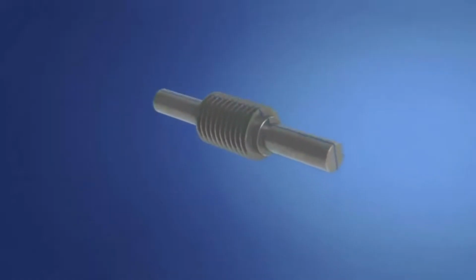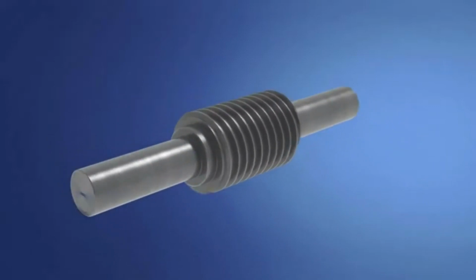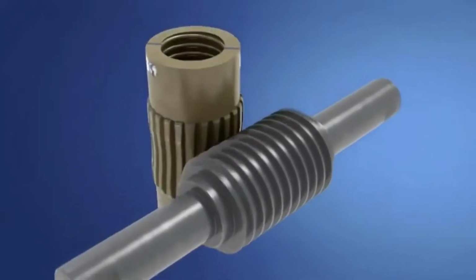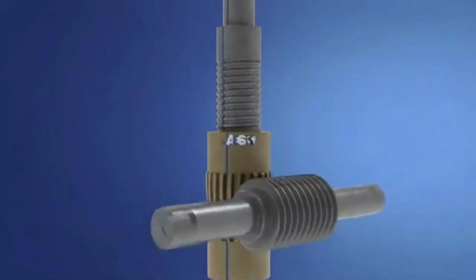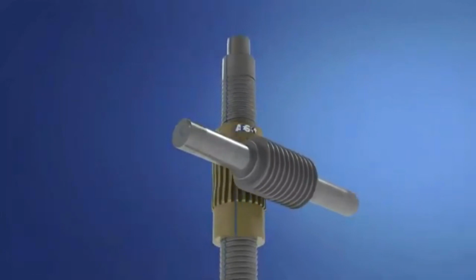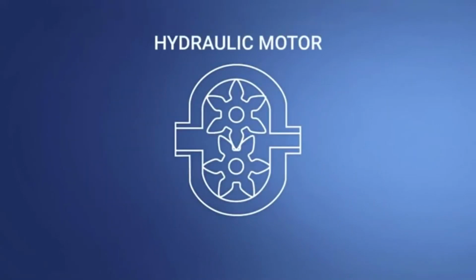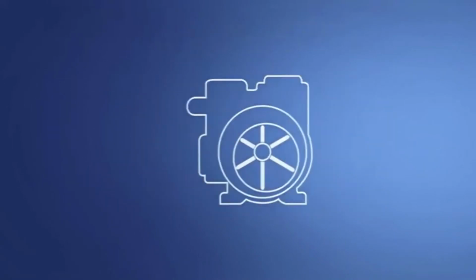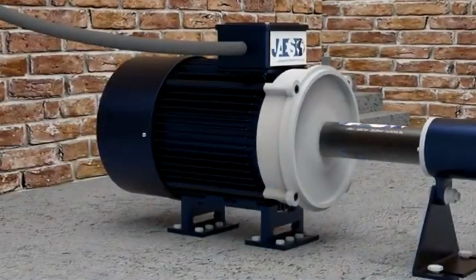A screw jack, also known as a worm screw jack, is a device used to convert rotational motion into a push-pull linear motion. It utilizes the property of a screw thread, providing a mechanical advantage, which means that it can be used to amplify force. The rotary movement can be supplied manually or with the help of hydraulic or pneumatic motors, or electric motors like the induction motor.